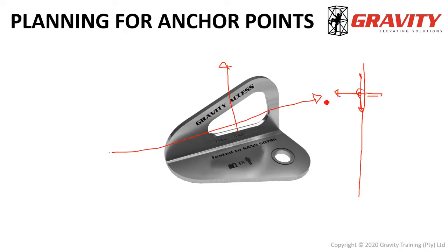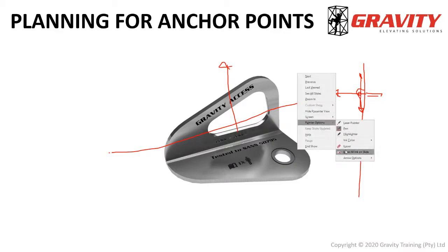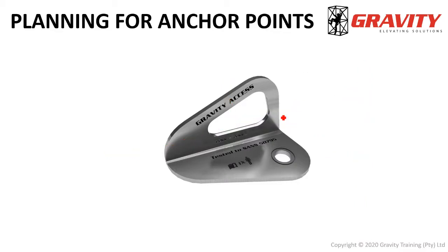Okay, so this is a special case of hangers where the hanger has been designed and tested to be strong in both directions. However, that's not the case for any and all hanger anchor points, so be very careful to follow the manufacturer's instructions and recommendations and the limitations given by them when installing and using anchors like these.